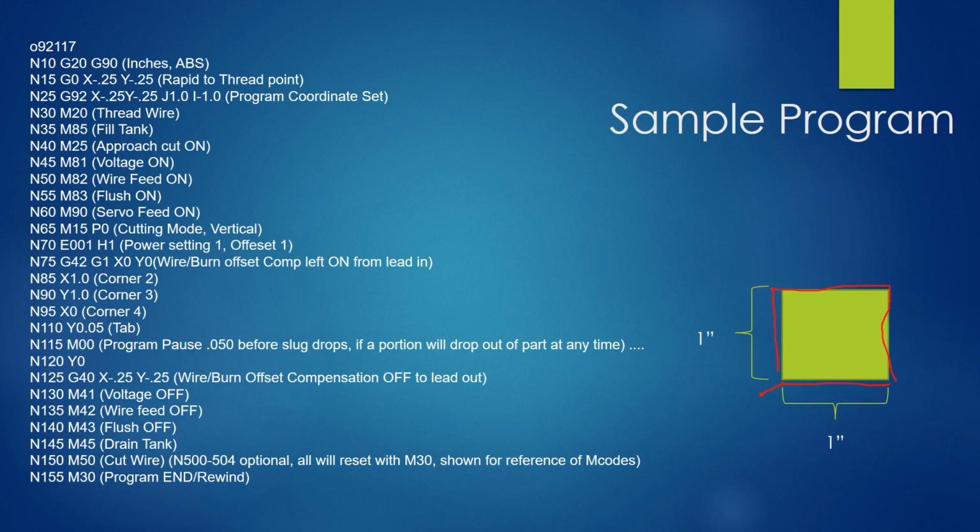The operator is going to hit the green button. It's going to cut through, and you'll actually hear it. It sounds like a hacksaw right towards the end of the part. You're going to hear a difference in the cutting. Right when that voltage drops to 0, they hit the red button to stop the cut, and then they're able to take that slug out.